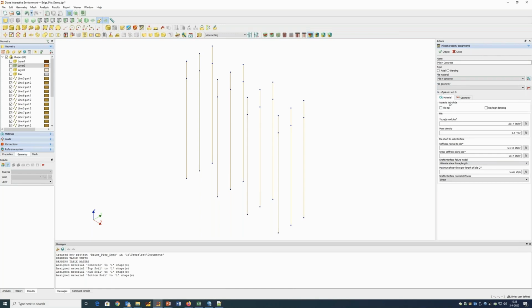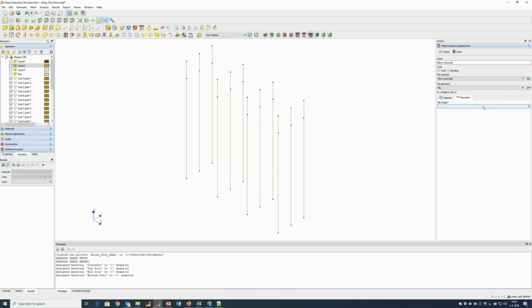And you can see here that I have all the properties that were in my table, basically. So the pile properties, the pile shaft to soil interface properties with their stiffness in normal and shear direction, and the ultimate force. And for the geometry of the pile, I'm going to define 1 set, which will be circular pipe shape, a diameter of 0.7.